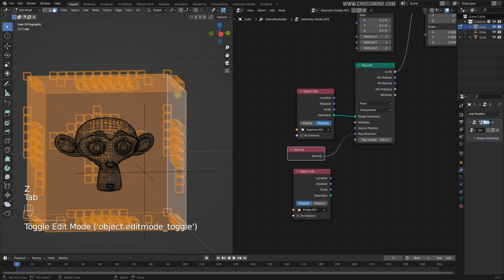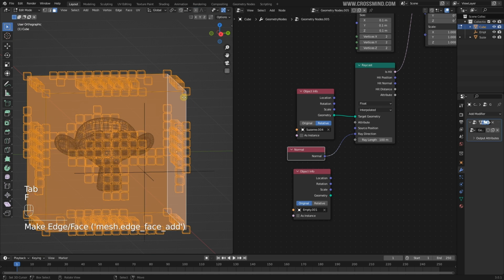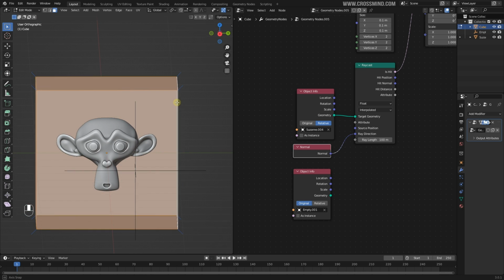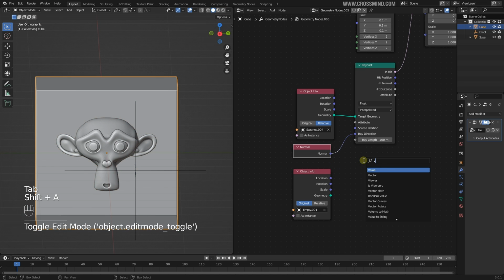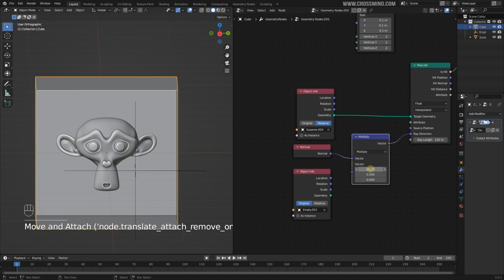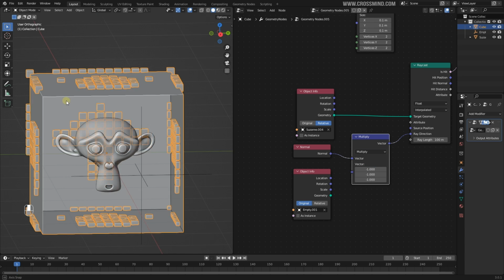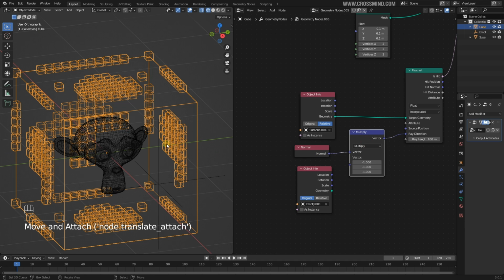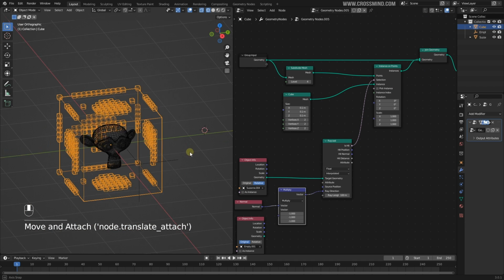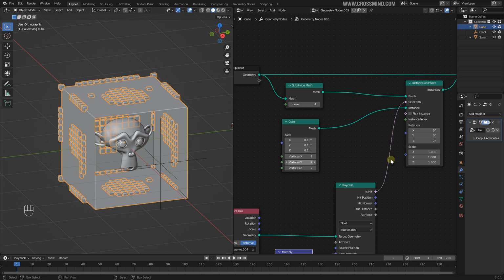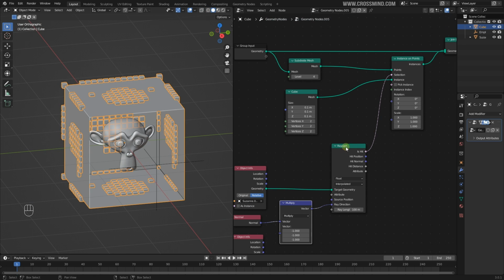If you don't want to flip the normals in the object level mode, so let's say if you are rendering this object and you don't want to flip the normal, then you can always bring a vector math node here in the geometry node itself and multiply the normal with -1. So that is going to flip the normal here, the input of the normals. So that does exactly the same thing, but in a much more convenient way. So anyways, this is pretty much the basics of how you use the raycast.